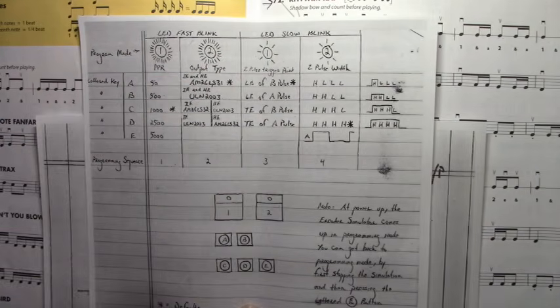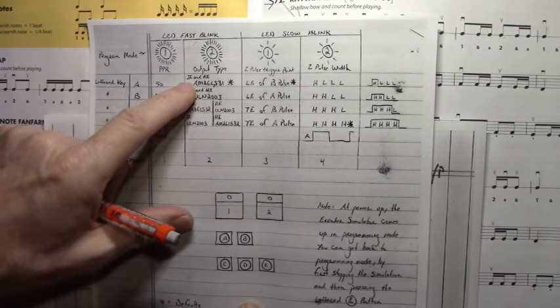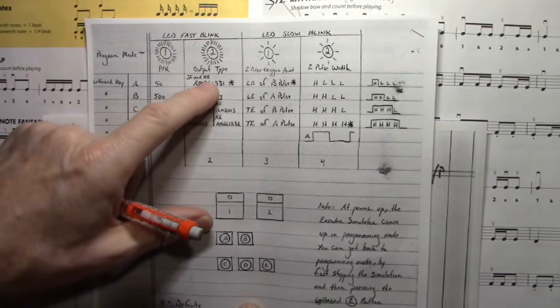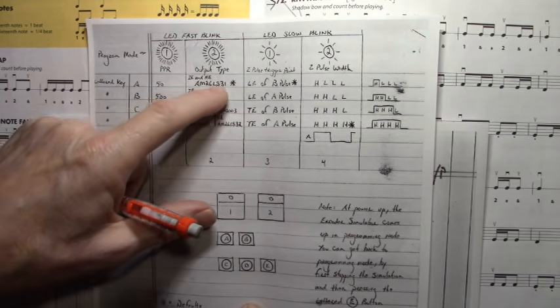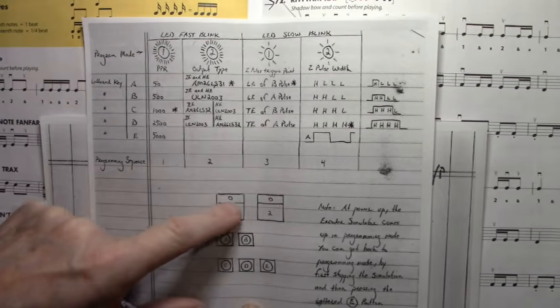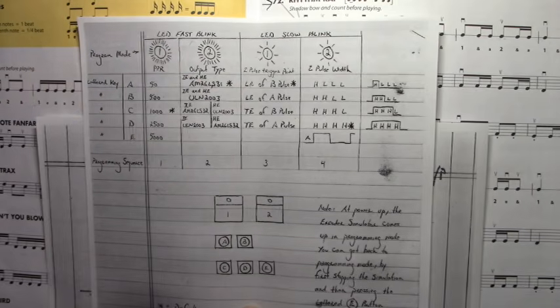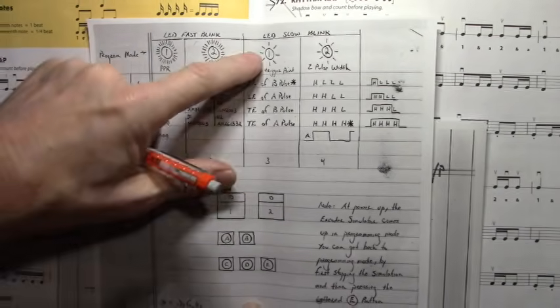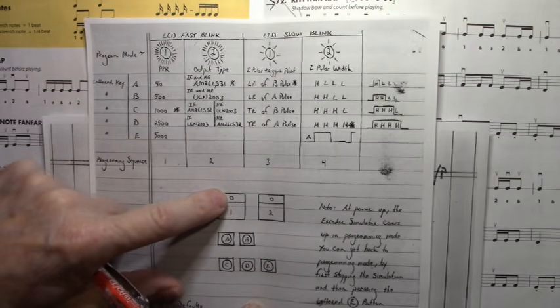Now if you want to default to incremental encoder and Hall effect going to the AM26LS31, the differential output, you would just push the number 2 switch right there and it will default to that value. So now we're over here back to this switch, but the LED is blinking slow.